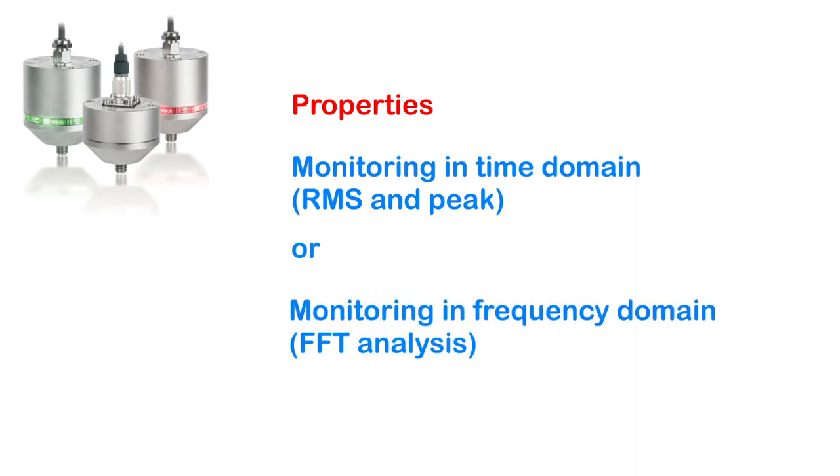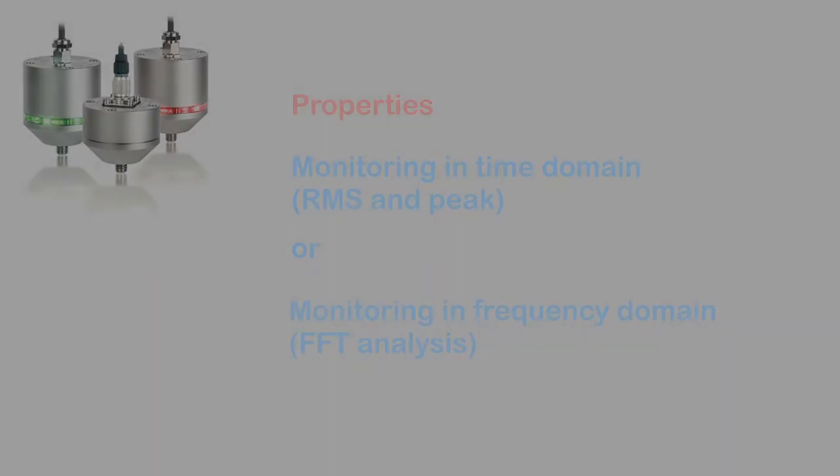A special feature is the frequency domain mode, which means that the vibration switch continuously performs a frequency analysis. The vibration signal, often a mix of frequencies, is divided into its frequency components. This allows a much deeper insight into vibration phenomena than the common wideband monitoring. Frequency analysis is a useful tool to find the source of a vibration problem.